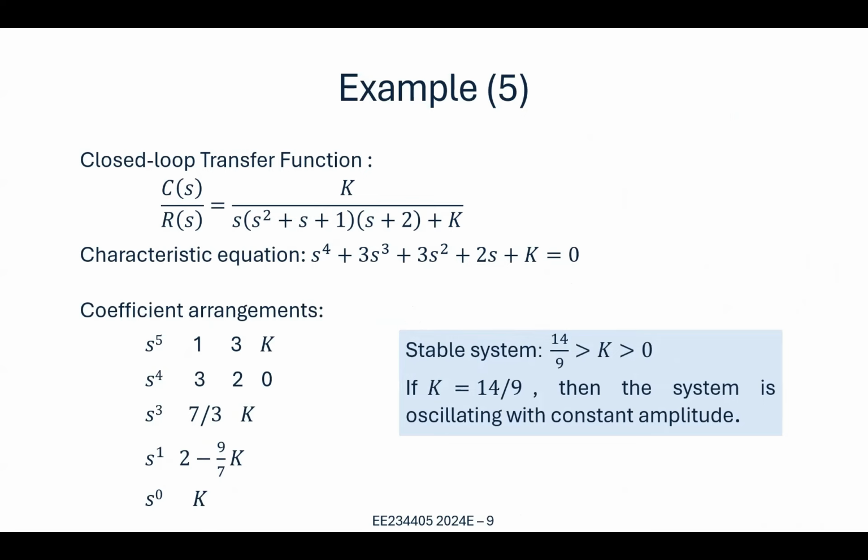Here we see that we don't really need the exact value of the pole to know whether or not the system is stable, and this is very useful to address systems where the denominator has higher order, more than 2. It's already hard to obtain the pole.